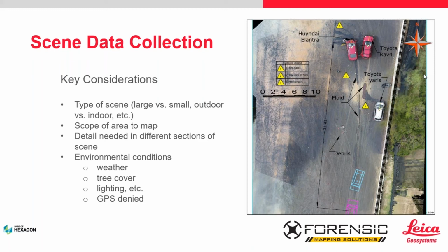Also, the Pix4D aerial photogrammetry software will give you a point cloud, kind of like you're used to seeing out of a laser scanner. The difference is that the resolution or the detail of the point cloud versus the detail from a laser scanner are different. But to cover an overall area or a large area, the detail of that scan for the whole scene is good.